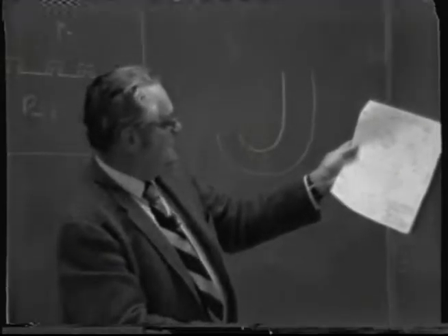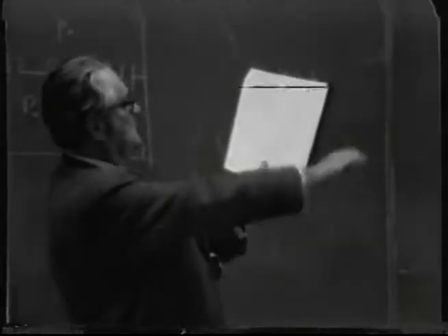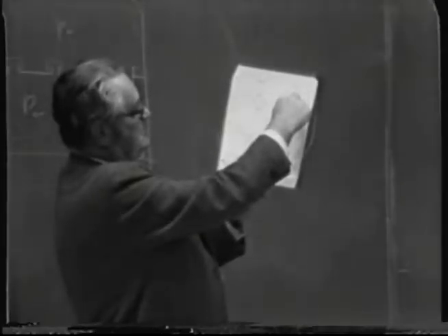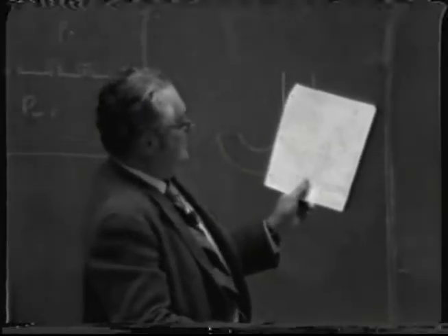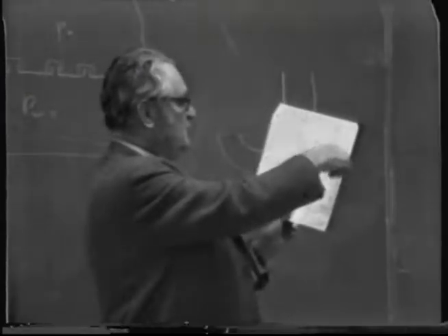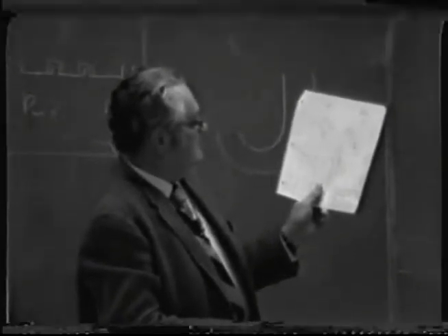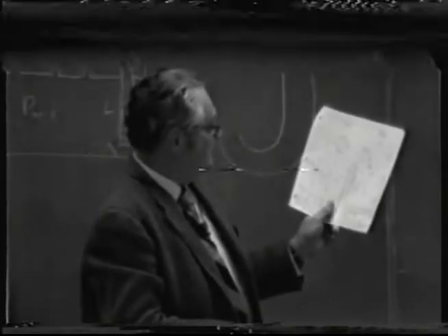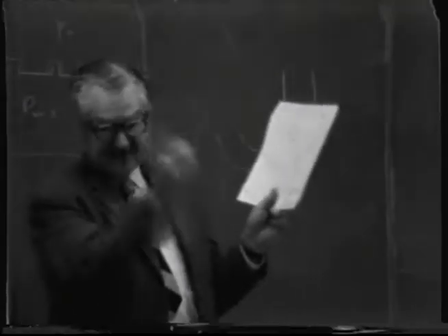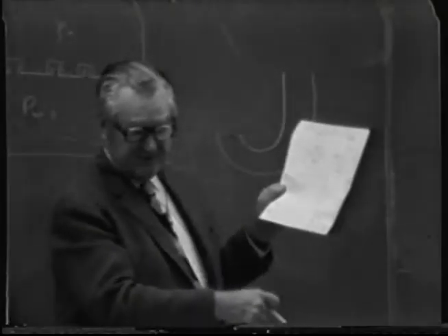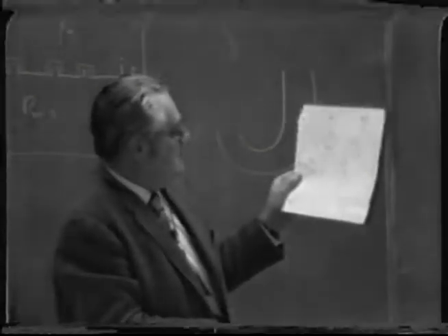And the other one is somewhat better, but it's equally poor in that they have two J-type downcomers here, and the overflow tubes for the next tray located uniformly around the perimeter of the column. So again, you have a rather short path to travel for the flow. But the worst part of this layout was illustrated by the two drawings below, which represent pretty closely the dimensions as I measured them in this column.